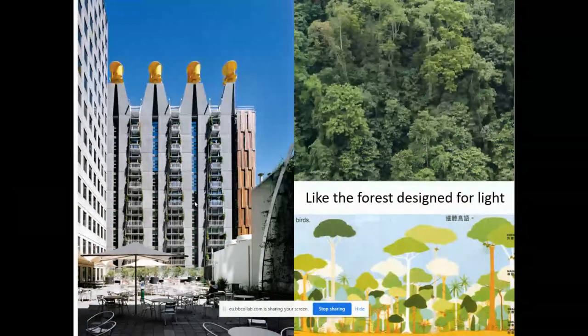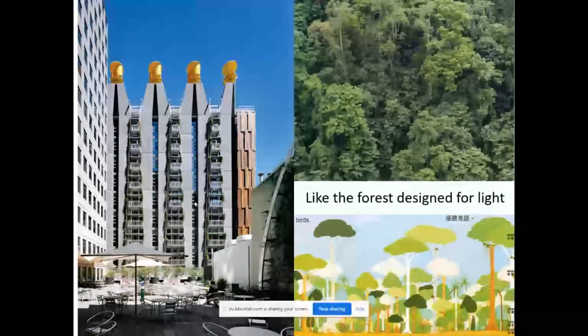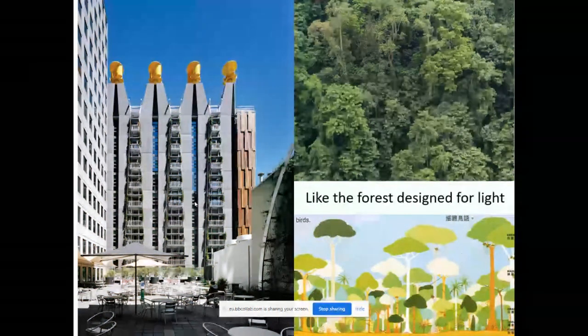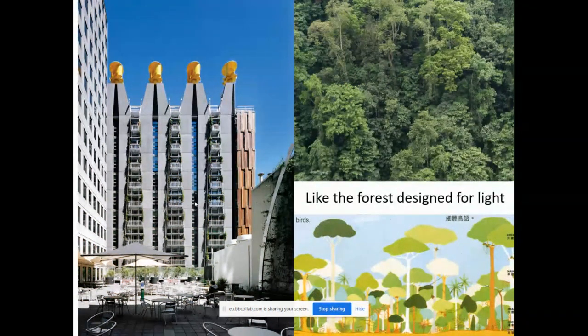We chose the Savonius vertical axis turbine because it doesn't mind. It's meant not to mind the direction of the wind, but we made them too heavy. Something we now regret. It was a nice idea, but I wouldn't do it again. Actually, it's not worth the while. They look nice.